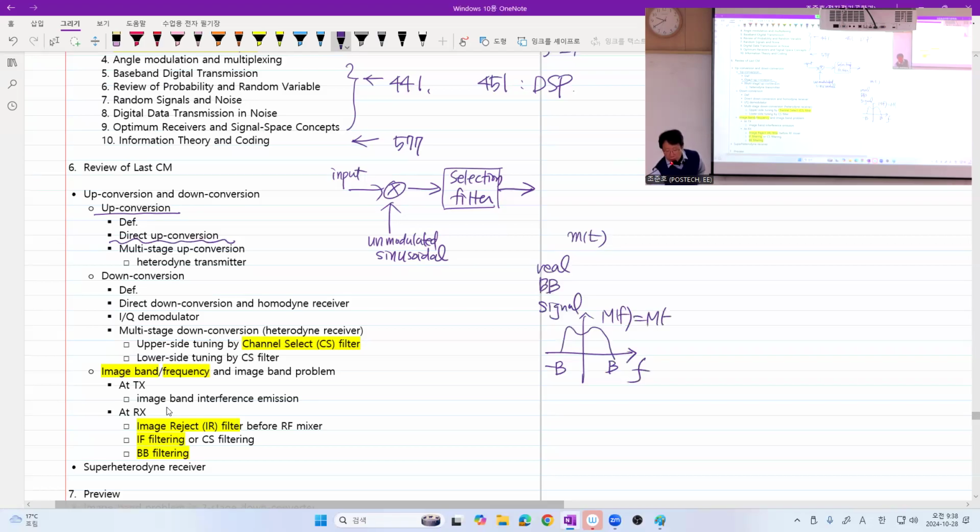The Fourier transform must satisfy conjugate symmetry because I assume the signal is real valued. However, when you study digital communications, and also when you remember single sideband modulation, the message signal that serves as a complex envelope of a real valued bandpass signal is not necessarily real valued. However, in the beginning of wireless voice broadcasting or communication, the engineers at that time had